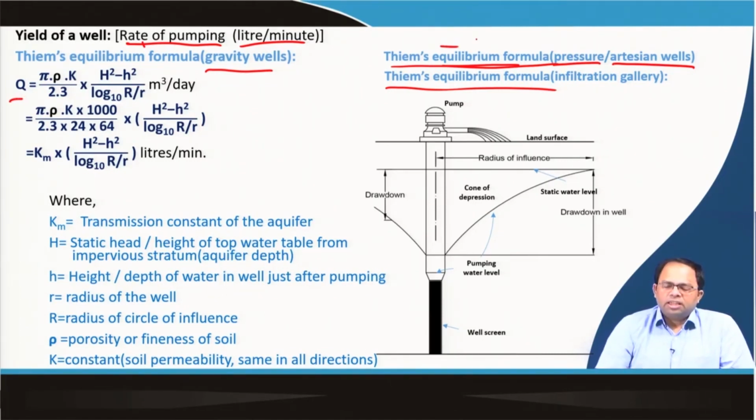Also you have to understand, this is a deep tubewell that is put inside an aquifer, and we assume that the entire aquifer's depth is being utilized by this deep tubewell, and it has openings on the sides through which water enters the pipe of the tubewell. That means that instead of the lower part or the cross section of the well, more important is the surface area of this particular well. Surface area is basically 2 pi r, the circumference, into the height. So this is the surface area of the well through which water comes in, right?